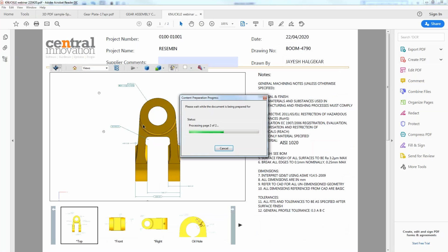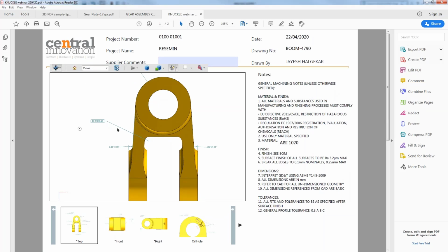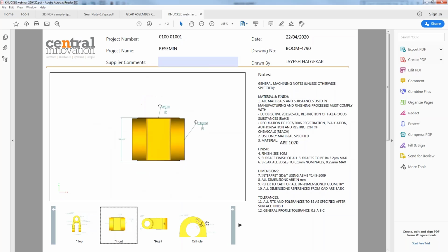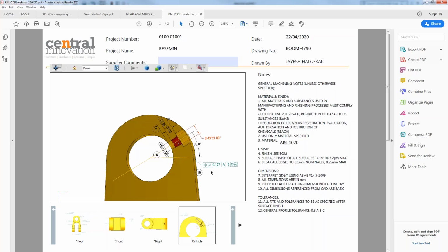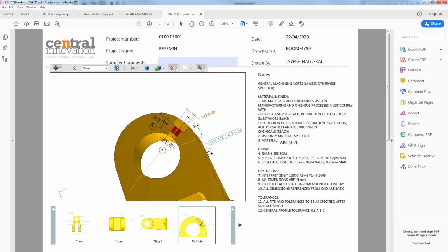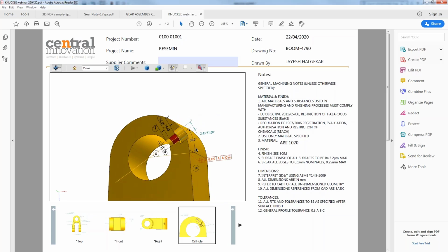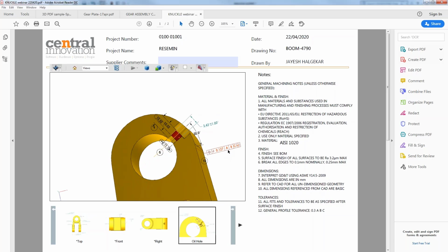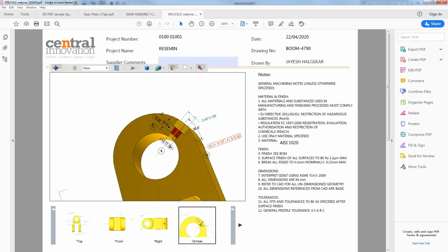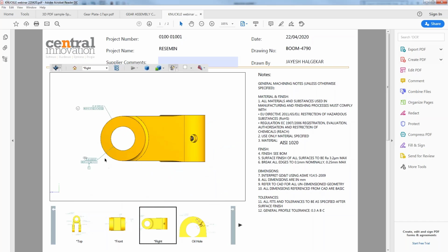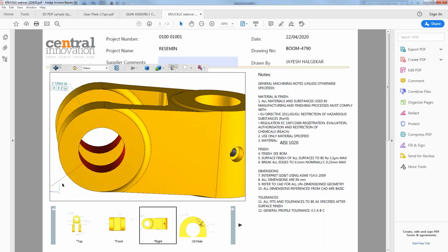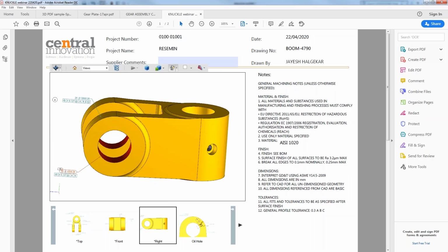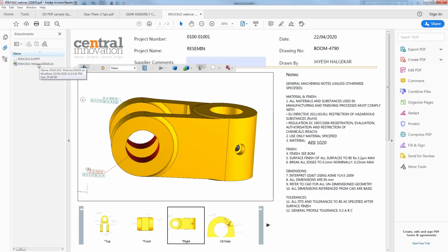I forgot to do the settings for the text size, so it's basically not got the right text size for me, but that's fine. So what you basically have here is all that information with the balloons added into this program. So for my inspection team, I can directly send them the 3D PDF, and they can actually check out the details for this oil hole as well to see, okay, if they've had a measurement for any of these details. Same thing, this is my key characteristic. So this is the holes that we need to measure for the key characteristics and feed it into my inspection project.